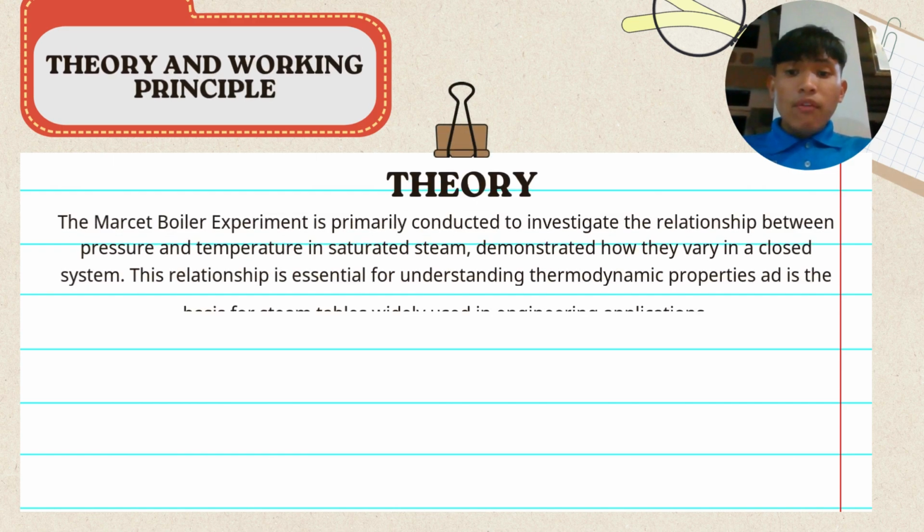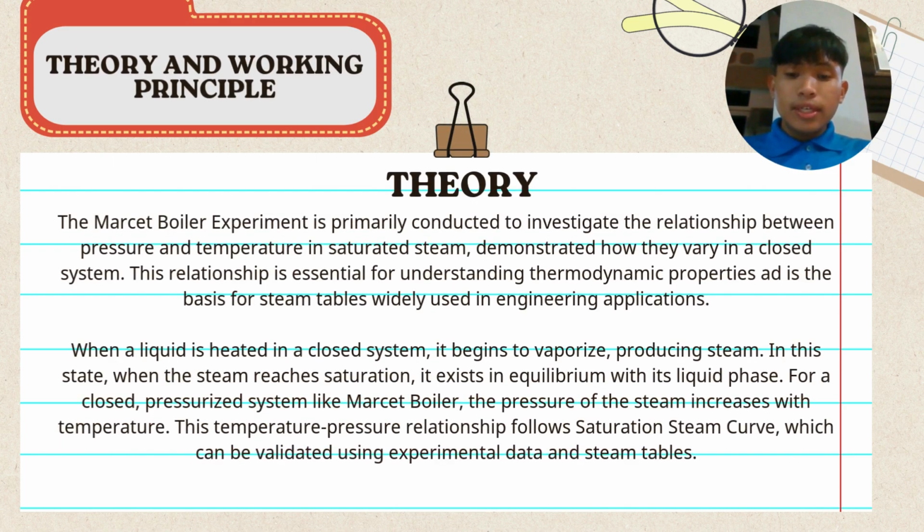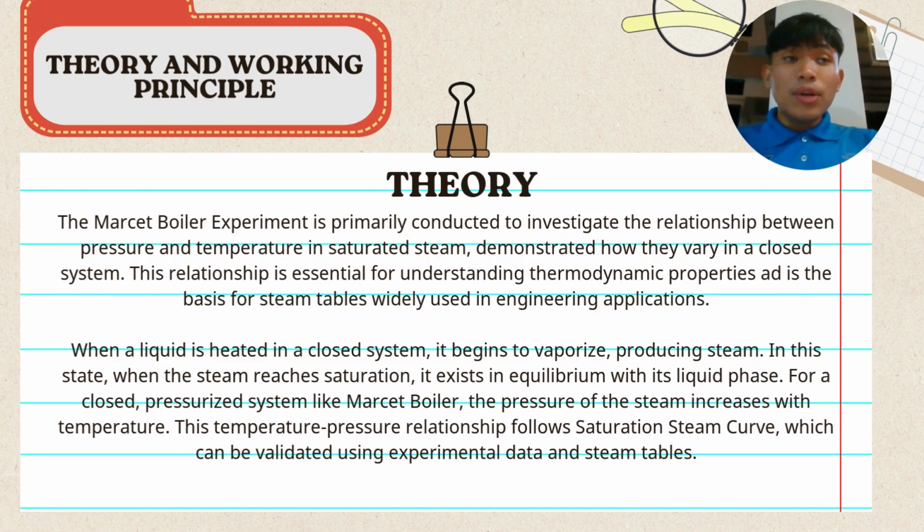Okay, thank you, Afina, for the explanation of the introduction for experiment 1, Marcet Boiler. Now I'm going to talk about theory and working principle, but first let me introduce myself. My name is Fakhrul. The Marcet Boiler experiment is primarily conducted to investigate the relationship between the pressure and the temperature in saturated steam, demonstrating how they vary in a closed system. This relationship is essential for understanding thermodynamic properties and is the basis for the steam table widely used in engineering applications.